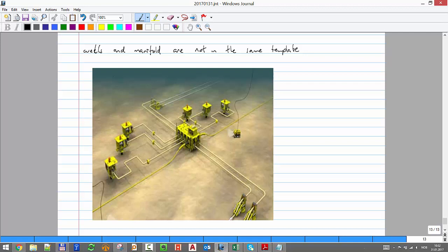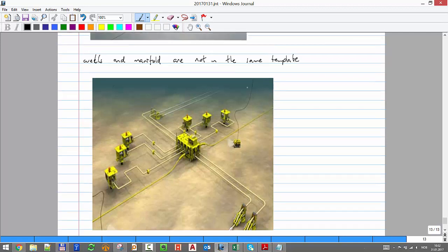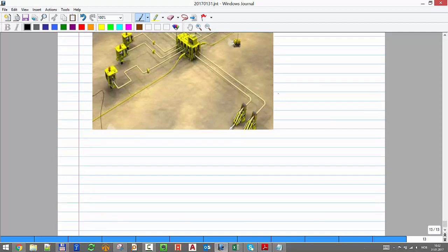And in this case also, in the other one you have just 4 slots, and in the North Sea usually we use 3 and have 1 for backup, if one of the wells is screwed up. But here we can connect as many as we want. The main limitation is the capacity of the manifold. How many entries can I have in the manifold? So those are some of the advantages and disadvantages. So in cluster, yeah, we can.